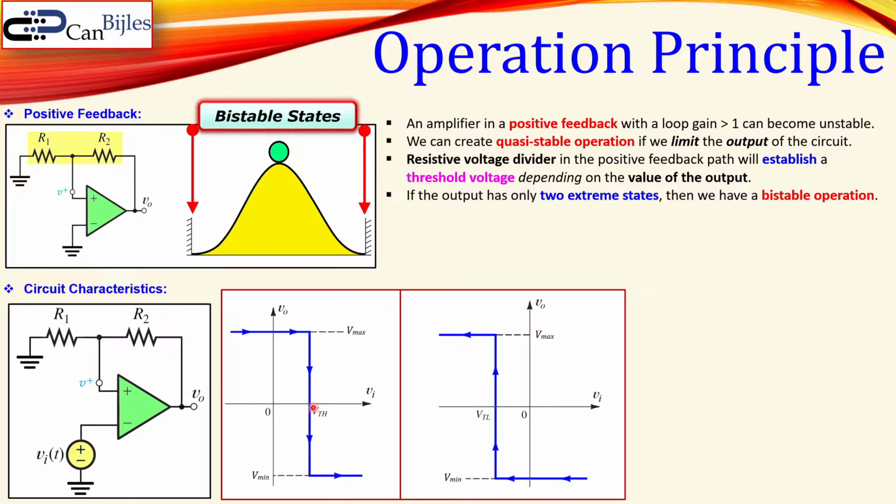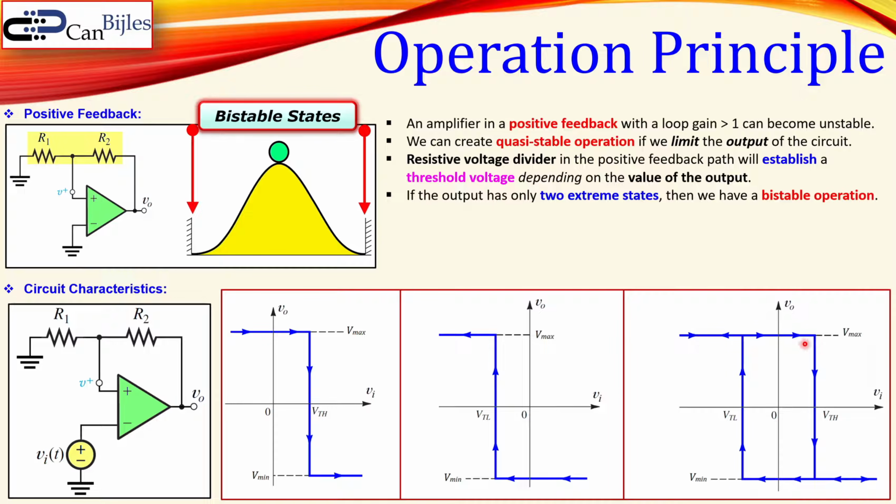So there is a threshold high and a threshold low, so it is not triggering at the same voltage level. Now if I go back and look at this relationship, we can also combine these two graphs together and create this nice Vi over Vout characteristic.